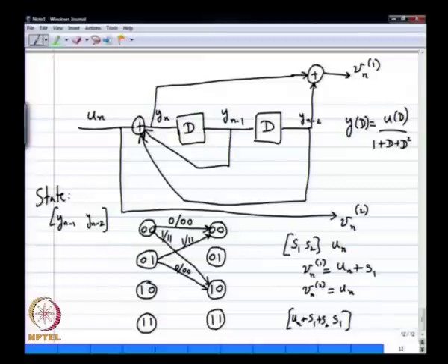Is that okay? Now you know the trellis by symmetry what should happen to the transitions. It is very easy to fix the transitions now, right. From 1 0 you should definitely go to 0 1 and 1 1, likewise from 1 1 you should definitely go to 0 1 and 1 1. Again in a well designed trellis all this will be true, okay.